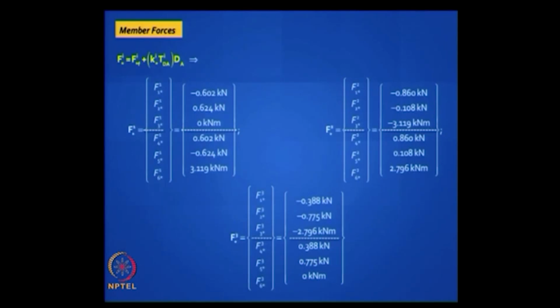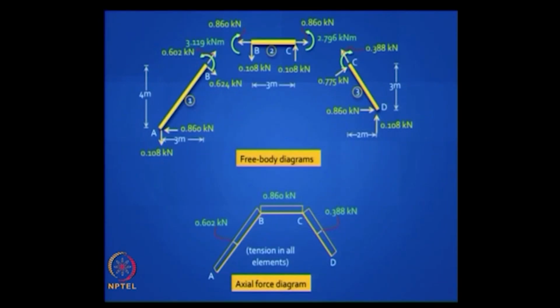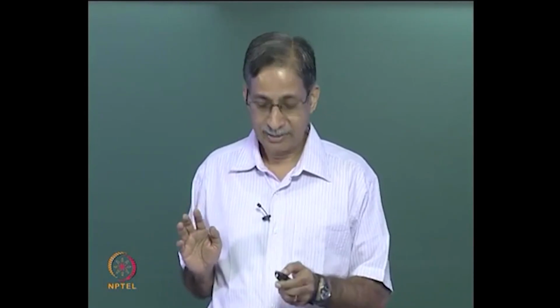You see that value which we got, 0.9 for the second element, the exact answer is 0.86, which is close to 0.9. So, and these are your final diagrams. You got your axial force diagram, shear force diagram, and bending moment diagram. The axial force diagram is more critical among these, and you will find that they are very small. Okay, so this simple problem teaches us many things and shows us the power of matrix analysis. So now with this we finished the conventional stiffness method.